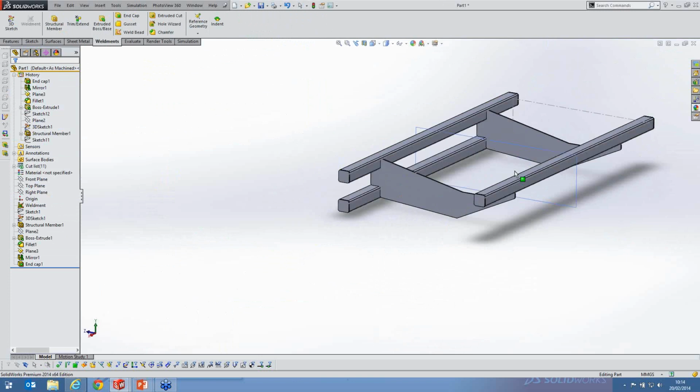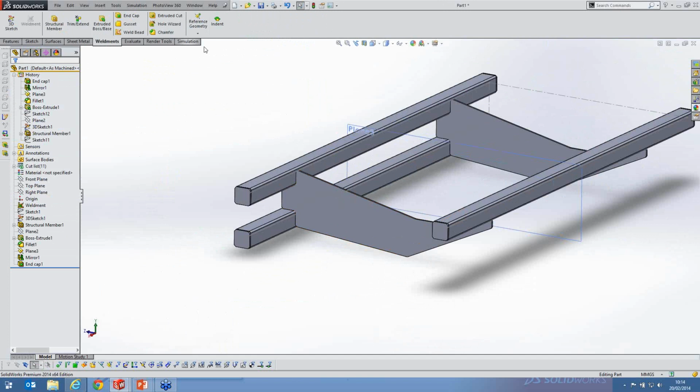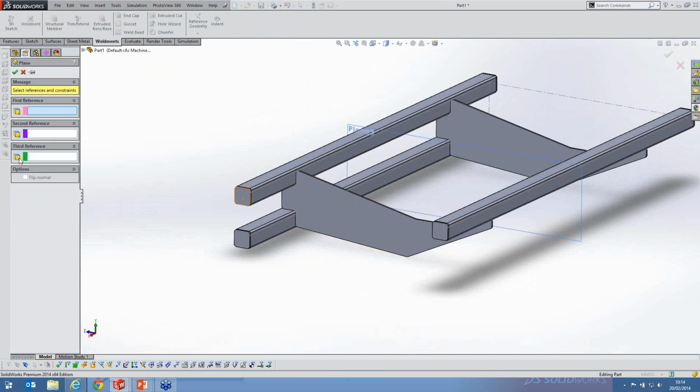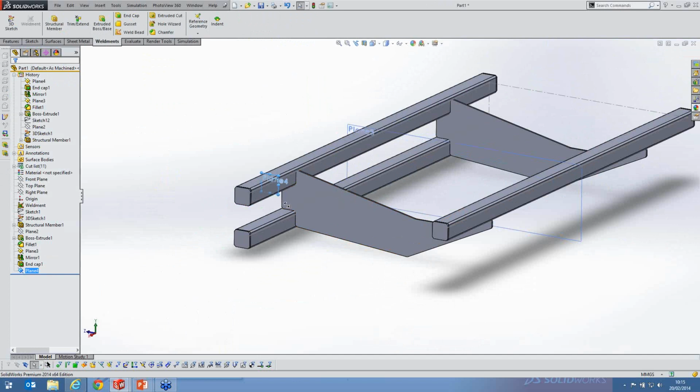Okay, so we've now placed our end caps on. The next stage for us is to create some other extrusions that we want to include on here. So we're going to have another reference plane created from this end face here at 300 millimeters, and that wants to be internally, like so. These planes are infinite in terms of their size, but we can drag those out and make them a little bigger visually if we want to.